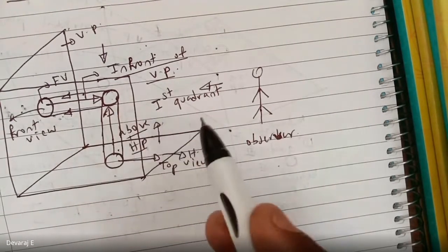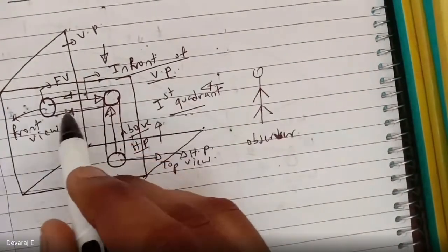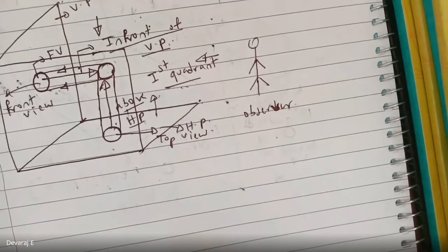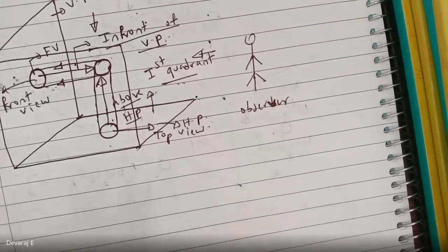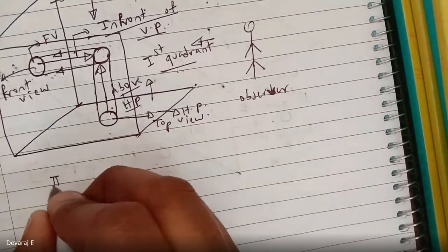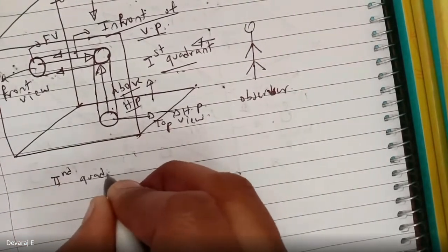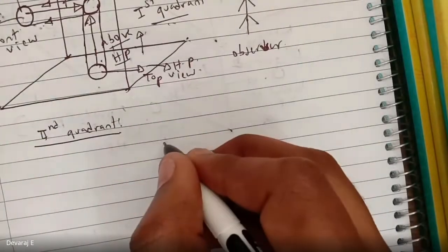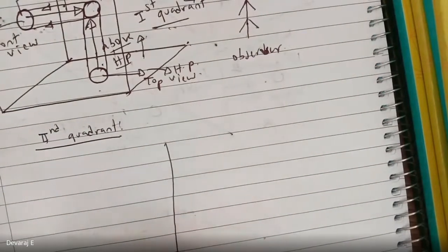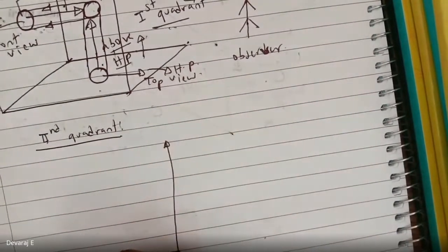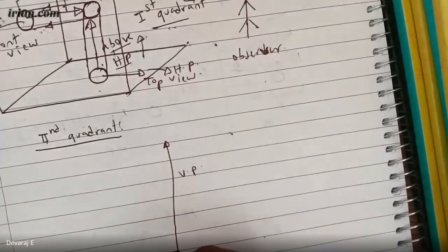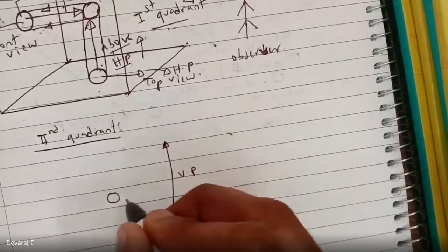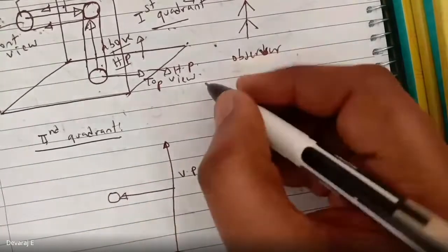So always you should remember, the first quadrant represents in front of VP and above HP, right? In a similar way, if you go for the second quadrant system, I'll write it in the form of 2D view. So this is your VP, vertical plane. This is your horizontal plane. So if you keep a ball here, this represents...